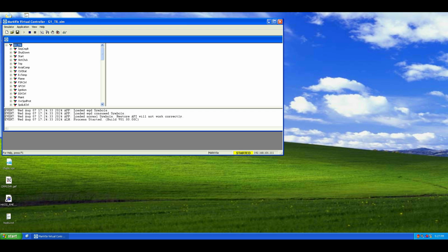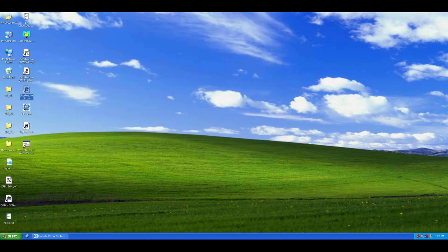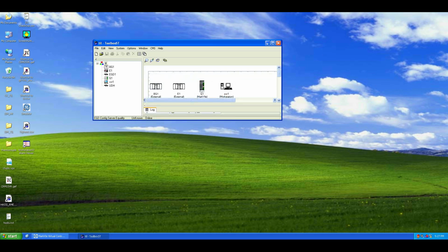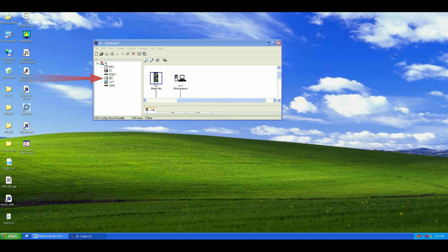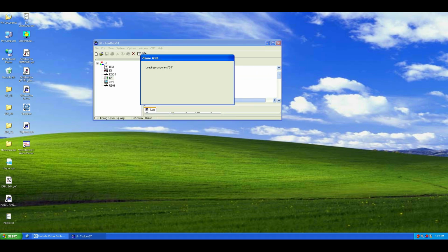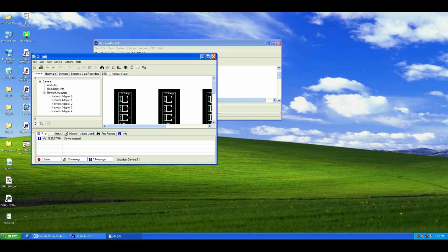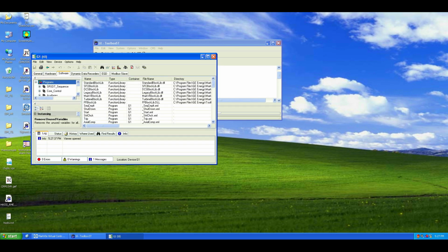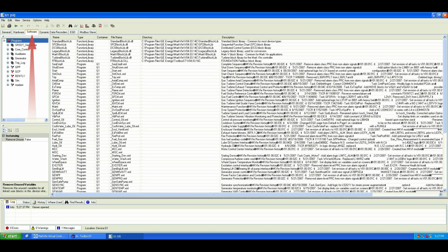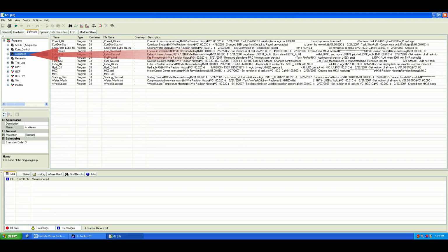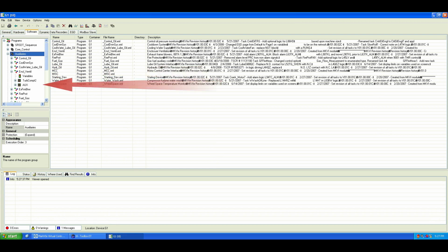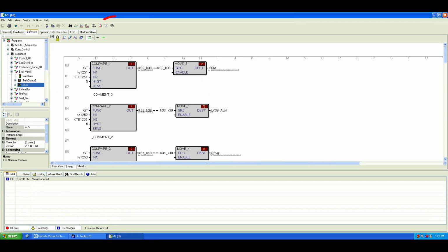Let's begin. First, start the simulation and run the controller simulation program. Double-click the G1 controller icon in the tree view of the system editor to open its component editor. From the Software tab, select the Auxiliaries program, then click Enclosure Ventilation, and finally select the auxiliary task. Make sure you're online so you can see live variable values on the block diagram pins.